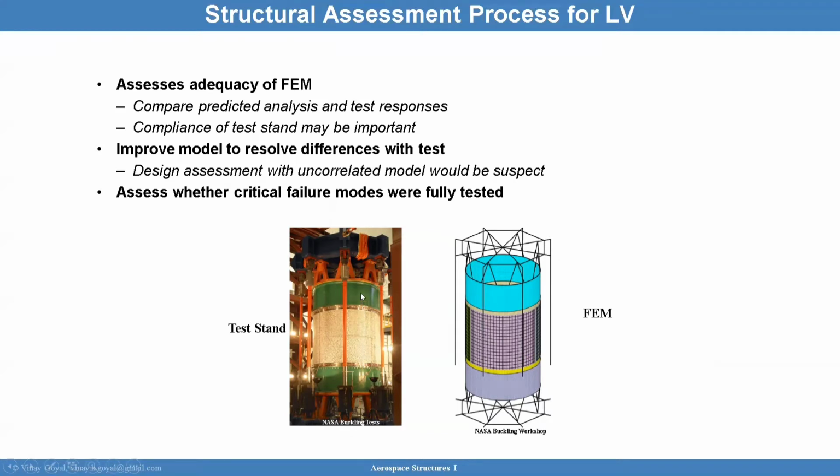So putting strain gauges in areas where the strain is not changing very much is useful, but it's also worth putting strain gauges in areas of gradients. That's okay. Bottom line, there could be a number of reasons why your strain gauges are not matching the test. Channels could be off, so you may think you're looking at a particular channel, but you're actually looking at a different strain gauge. And then maybe there's a strain gauge sensitivity issue where the strain readings are fairly low, and so you tend to be more off when strains are fairly low. But if strains are off, it may be worth looking at what's going on.